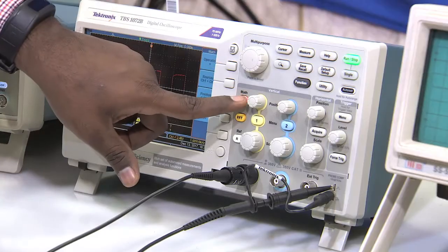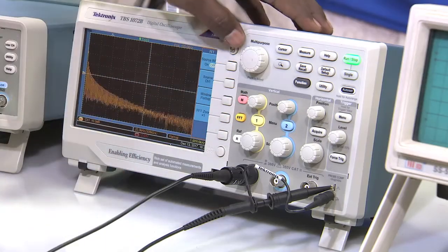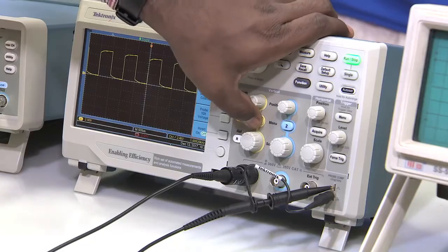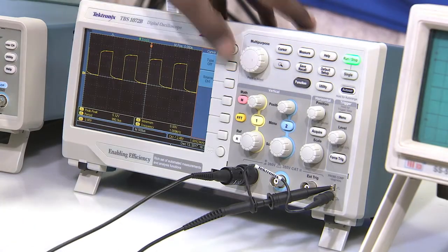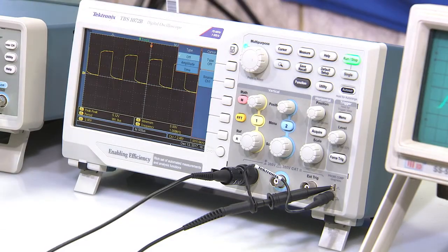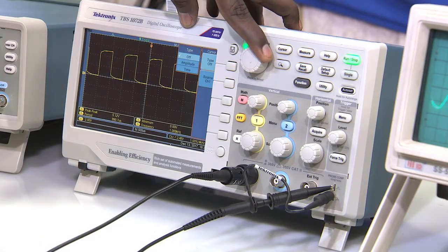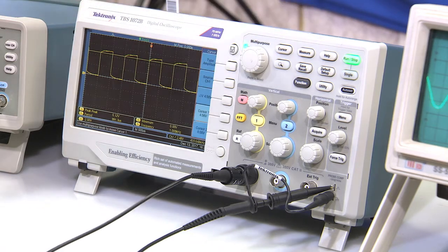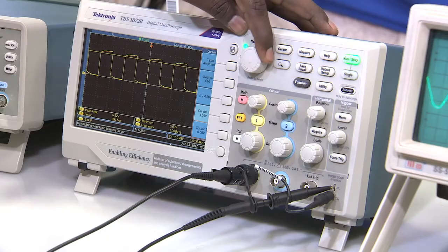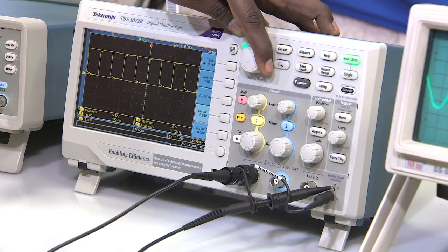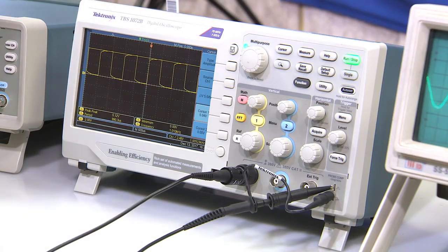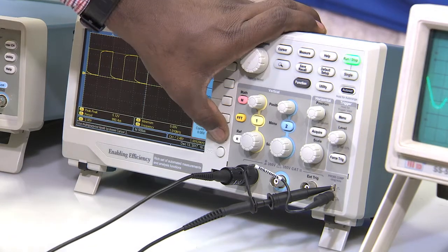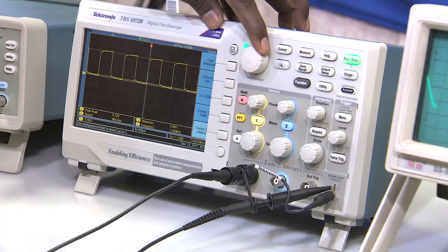So, these are several buttons on the oscilloscope, alright. Now, other than that we have cursor, right, on the top, and then you can choose whether you want it on or off, and whether it is amplitude or time. Let us say you want to use amplitude. If I press amplitude, I will see cursor 1 at the top of the waveform, and another cursor, cursor 2, you can have at the bottom.